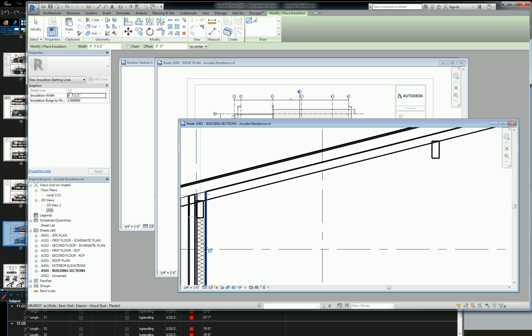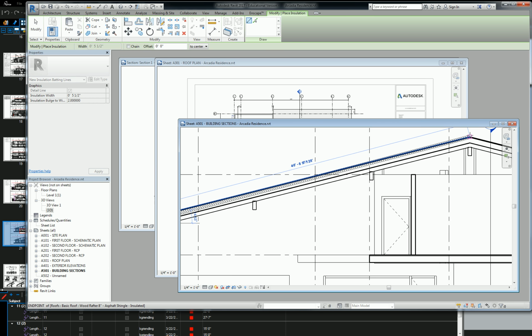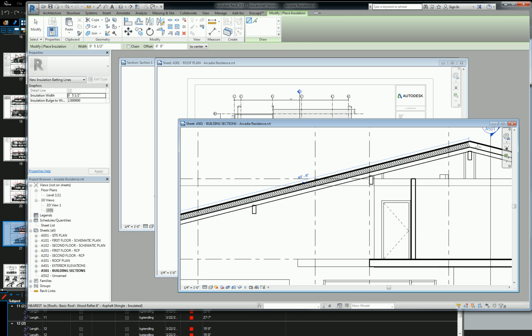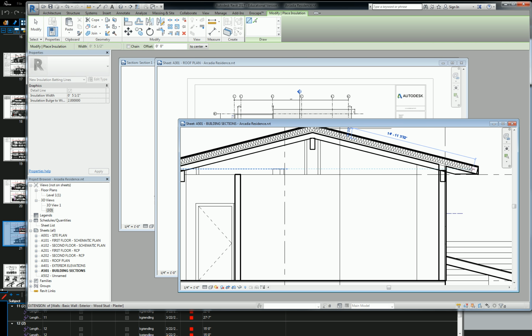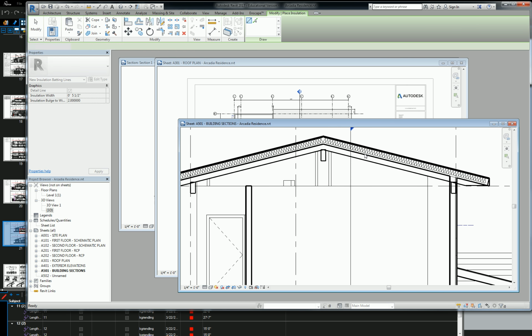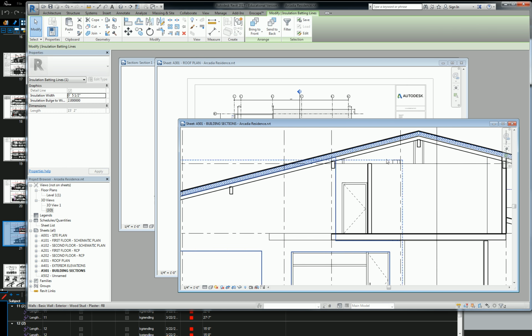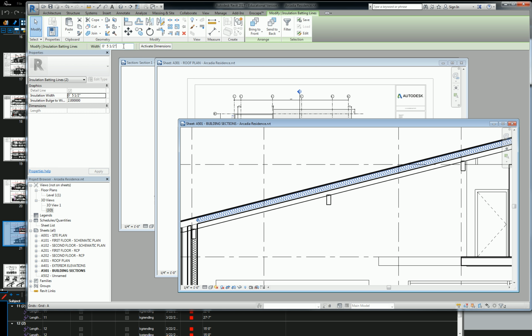And then with things like this, you're probably only going to put it in the actual roof cavity, not where the joists are sticking down. Actually, that's right. That line's going to go away. I'll show you that in a moment. But you're going to do 5.5 inches on the exterior walls, and you probably want to stick to like an 8 inch or something in the roof.